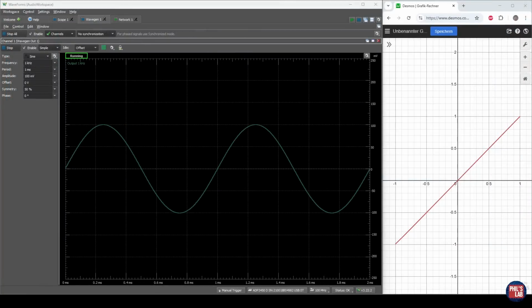I've now uploaded the firmware to this guitar effect pedal. Our overdrive algorithm is running, and we'd like to first of all test that before playing any guitar through it. We just want to see this in the time and the frequency domain. To do that, I'm using an Analog Discovery Pro by Digilent, which is a USB-based WaveGen and oscilloscope. I've selected WaveGen 1, generating a sine wave, frequency 1 kHz with an amplitude of 100 millivolts. That is connected to the input of this guitar effects pedal. I'm running at only 100 millivolts because of course we have a lot of gain in our guitar pedal system. The output of our guitar effects pedal is then connected to channel 1 of the scope.